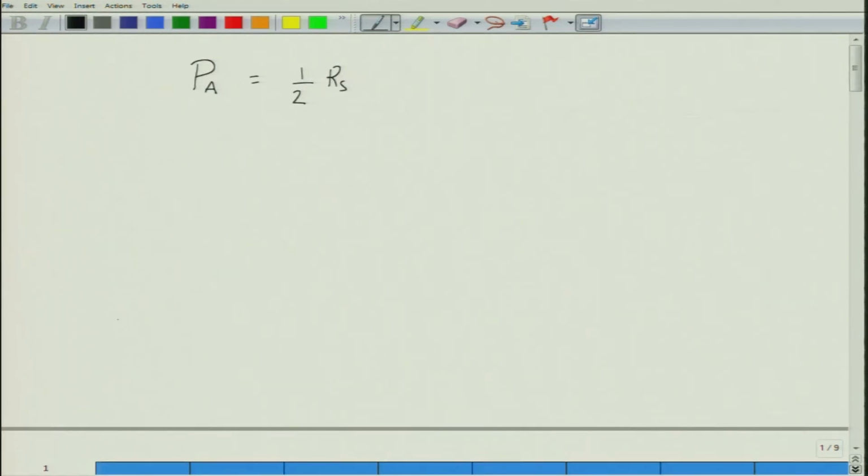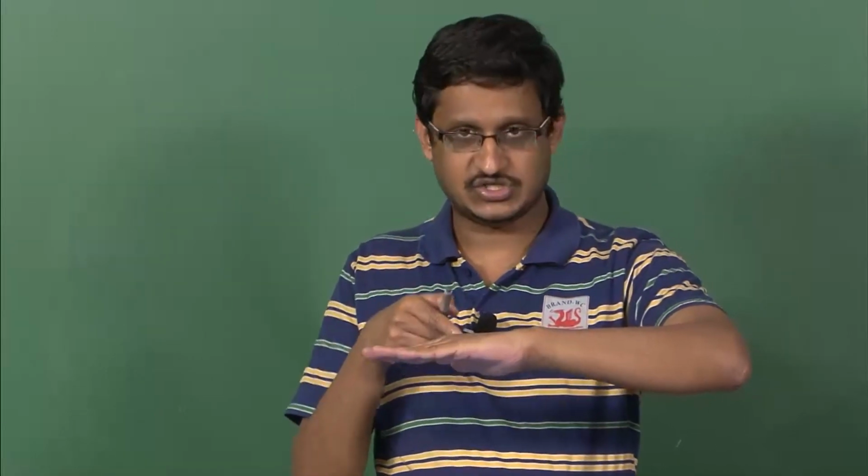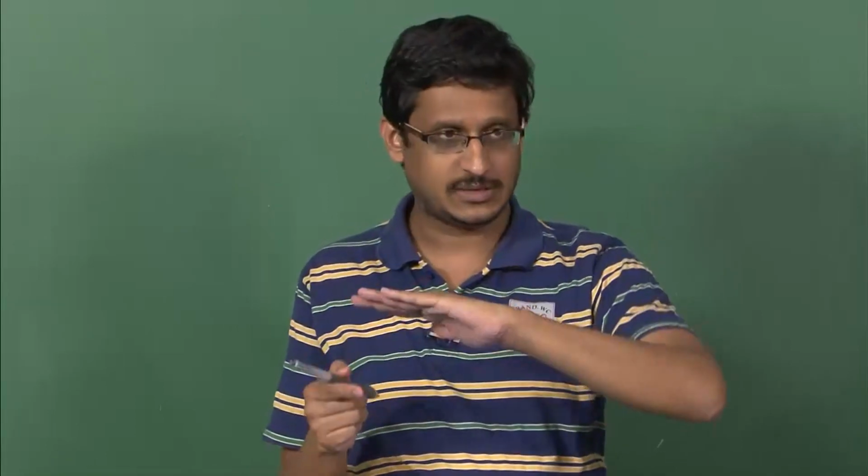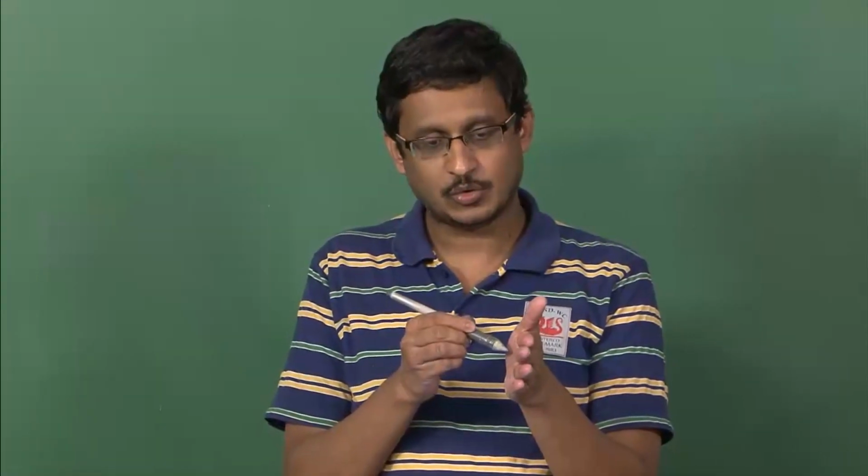In the example that we considered, you had Ex and Hx, and the current per width along this direction is related to the tangential magnetic field Hx for the case of plane wave incidence. So, in any wall, if you are able to find the tangential magnetic field on that wall, that corresponds to the current per unit width on that wall. IW is what we used in the previous discussion.